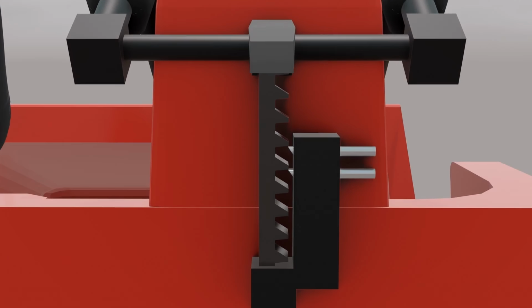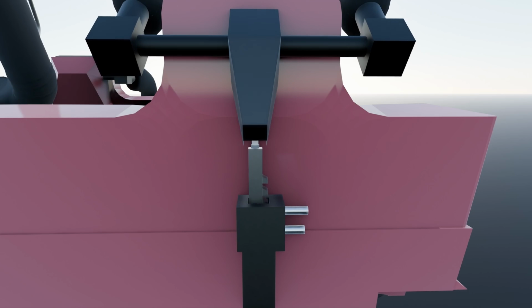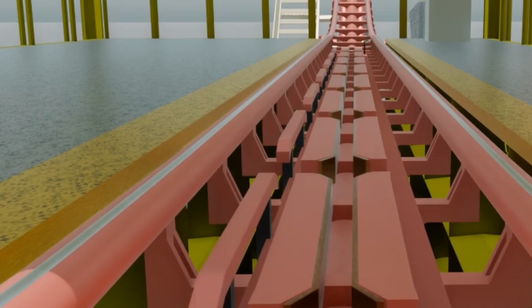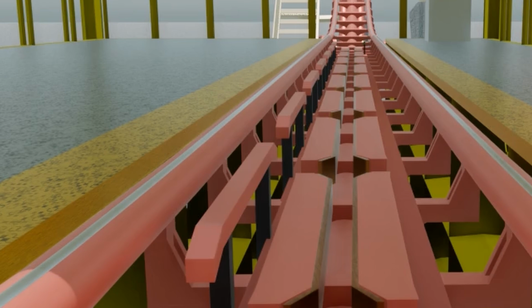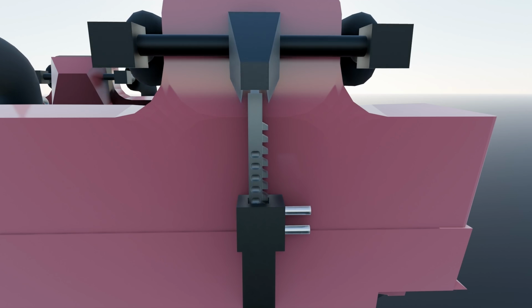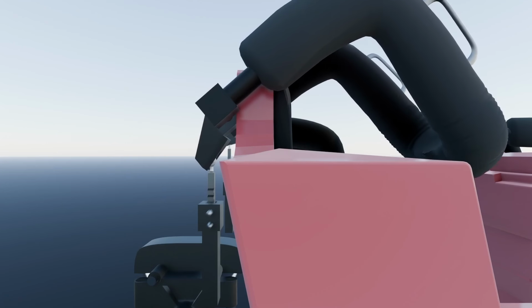This is due to the shape of the ratchet device, as when the pins are engaged, they will physically block the ratchet device from moving. These restraints are unlocked by an outside force, such as a mechanical bar or other system under the ride unit, moving the pins out of engagement with the ratchet device. These restraints can only lock in a fixed number of positions due to their design. These restraints are also known for making the iconic click sound when lowered.